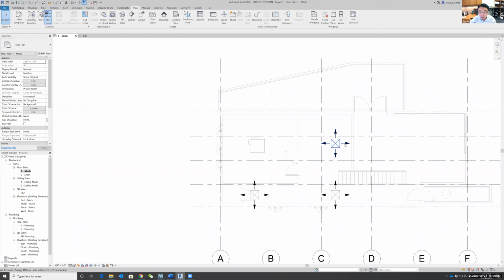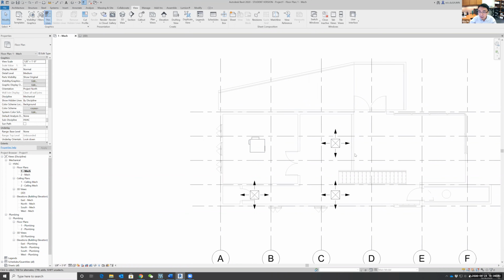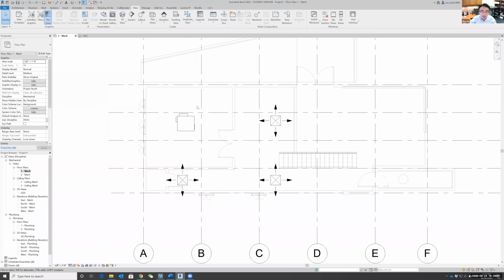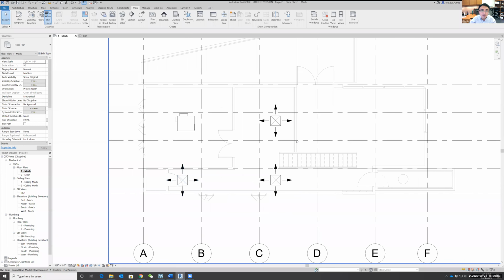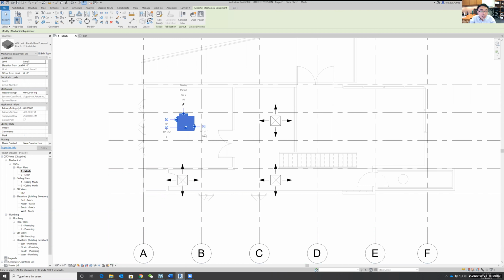Let's say I want to create some pipe, the duct system, to connect this VAV with all the 3 air terminals. So we need to create something called a system. So we tell Revit, this is my system, and Revit will generate the layout for me, okay? So this is how we do it. We just select the equipment. And once it's selected, let's say, Create a System. And we want to create a duct system, okay? So just create this one.